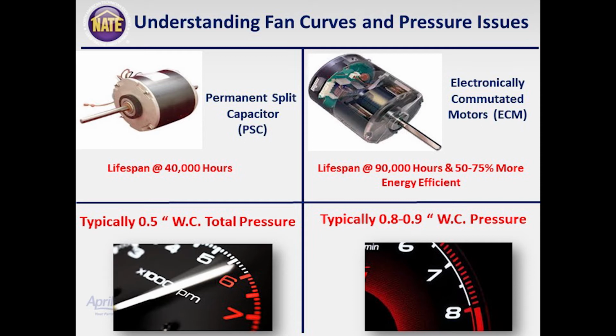Keeping that static pressure low is the best way to move the amount of air we need to give us good airflow, good heat transfer, and by keeping the blower wheel clean, keeping the A coils clean, by trapping stuff out of the air, we can give them that good heating and cooling efficiency that they bought their equipment for.